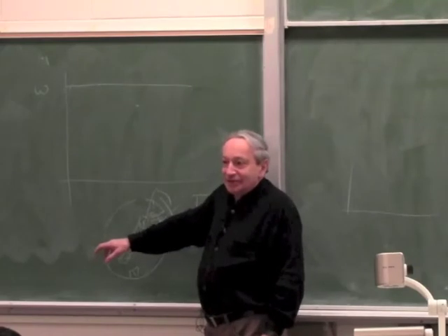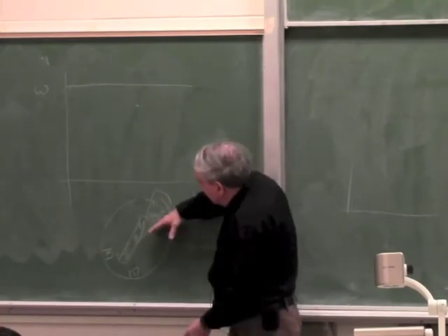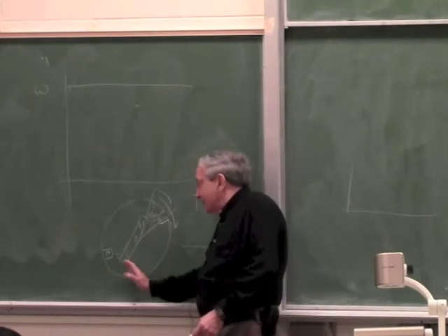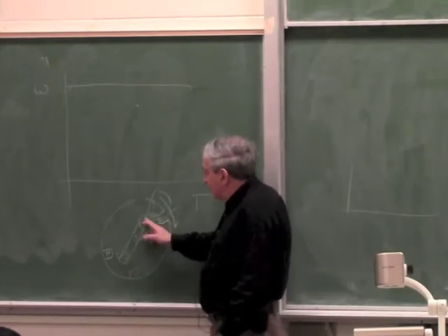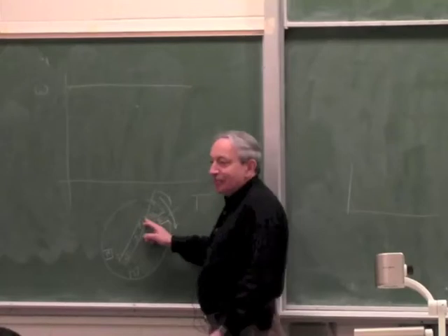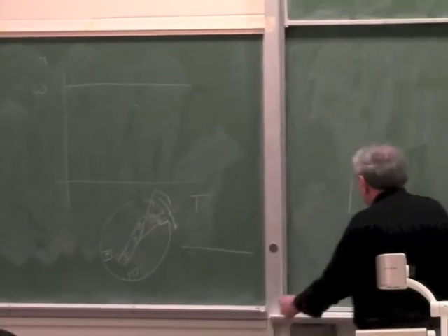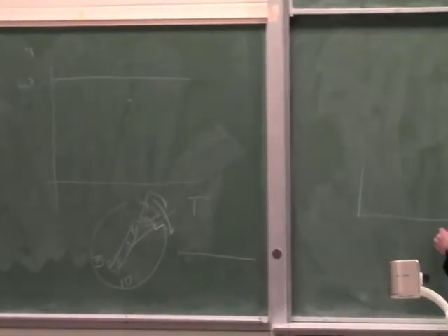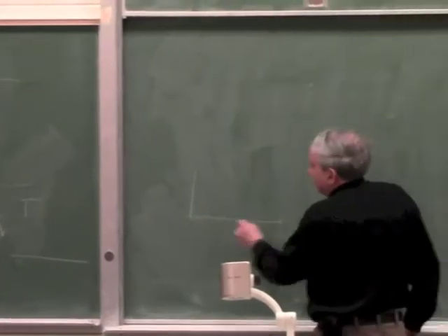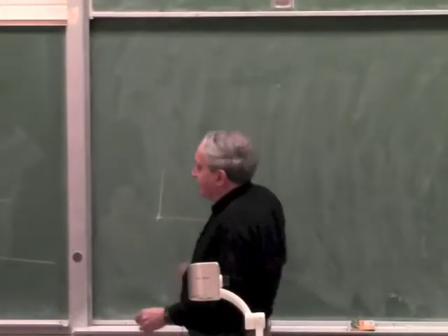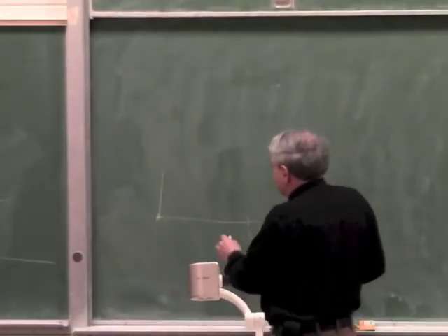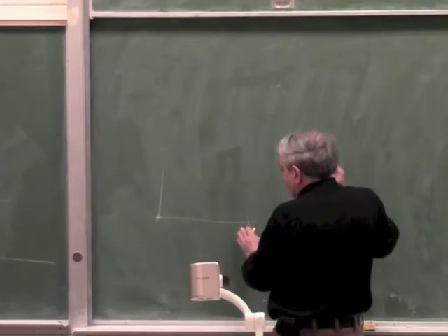So clearly, if the power angle starts winding up and goes all the way to here, it wouldn't attract this pole anymore. It will actually repel it. So the torque at 180 degrees has to be 0, and at 0 it is also 0. Now the reason for the power angle, so again, I'm drawing something else now.